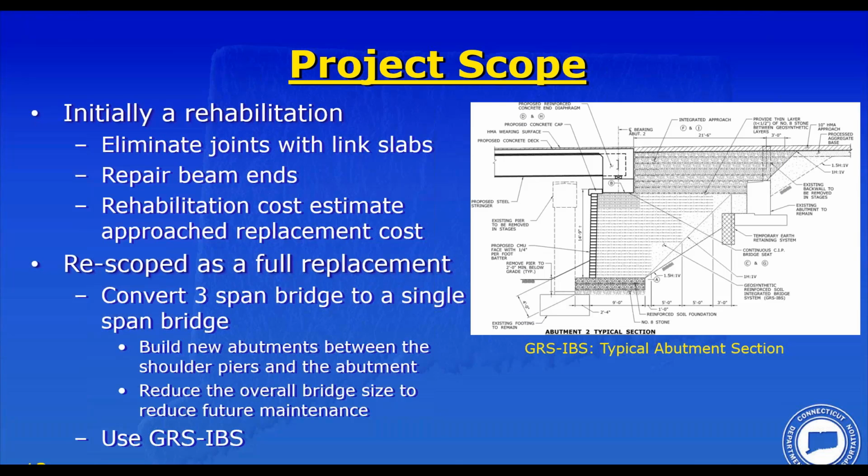Yeah, I see that. Okay, and then the next question is, what is the fill material? Is it a graded aggregate, or what? You're using local soil? What do you have for your fill material? That's a great question. You can use either. What's recommended is open graded material, essentially crushed stone, because it's easier to compact. So we typically specify an open graded material. And typically the compaction is usually 2 or 3 passes of a plate compactor to do an 8-inch lift. So that's the material of choice.